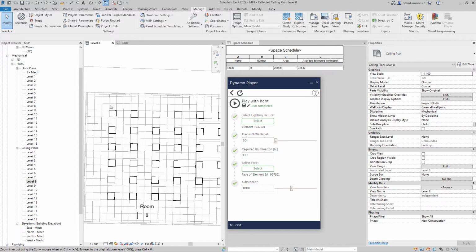It's the same with the Y direction. So if I leave 1.5 meters over here, it knows that it cannot go all the way over here to 1.5 meters. So that is why we have some clear zone over here, and because we did require 300 lux, now we cannot follow entirely that increment of 600.